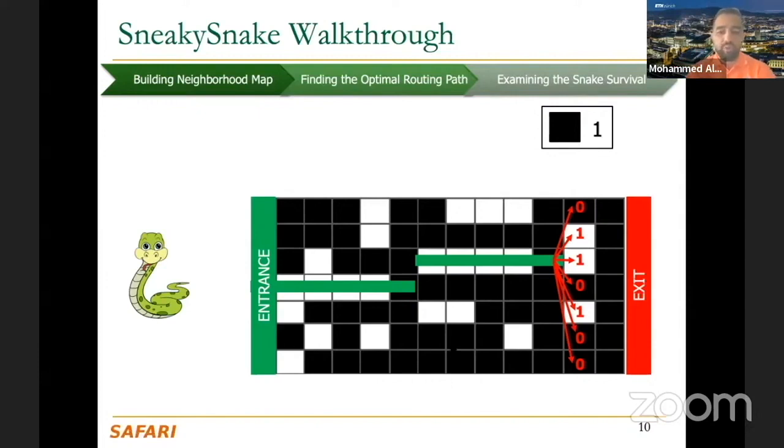Now, some of you could say, how come it doesn't matter? Because if I choose one far from this path, I'm going to use a vertical path as well, and that is a cost for the silicon or for the metal layer in the VLSI chip, right? Because we have multiple layers stacked on top of each other to have vertical and horizontal connections, and then soldering these layers far from each other, or this connection, might give you some cost, because you are going to occupy this entire vertical connection.